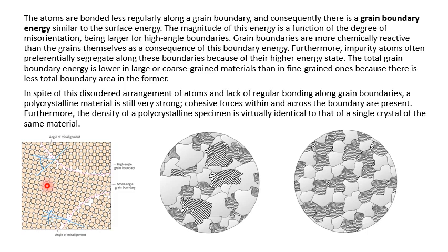And this is defined as the grain boundary energy, the energy of the grain boundary area due to having these kinds of defects, or the less bonded atoms in the grain boundary area. This energy increases with the angle of misalignment, being higher for high misalignment angles and lower for lower misalignment angles.